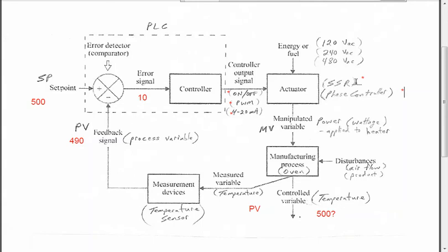A phase controller would be more precise control, getting right down to the sine wave, you know, to give a certain amount of the sine wave for each cycle. But these would be ways, and so it would be some kind of a switching element here, and then the manipulated variable is the wattage, the power that actually then is being applied to the heater.